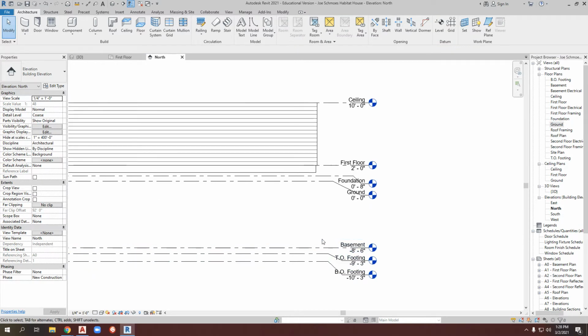And for that crawl space, I believe that we need to have the footing below the frost line. In our classroom discussions, we determined that 4 feet below ground would probably be all right. I believe that meets the frost line of the weather data that we use in class.